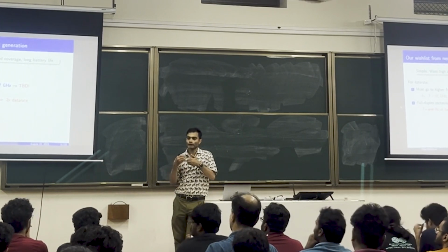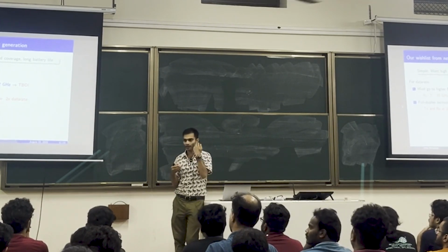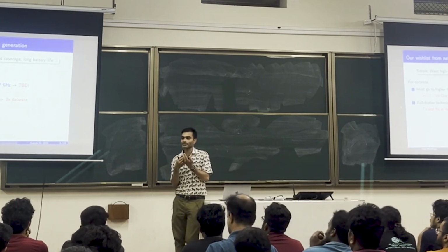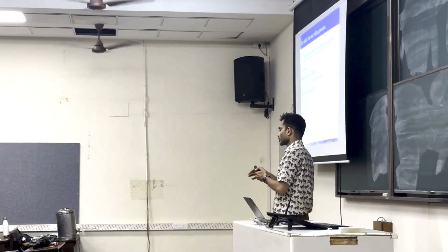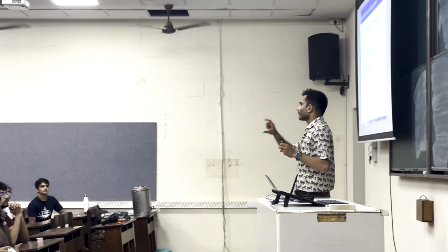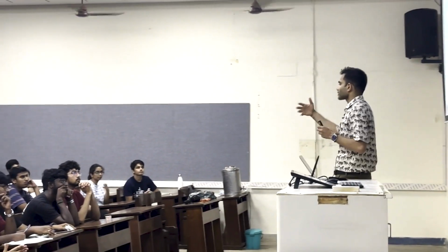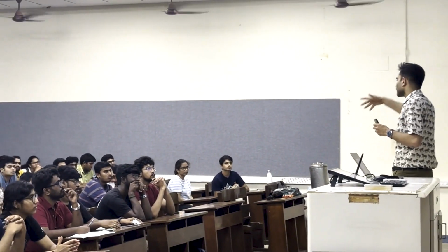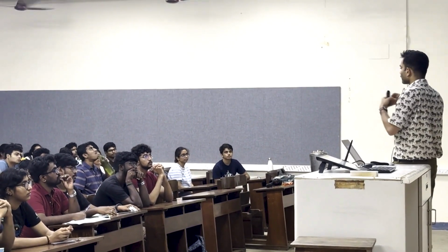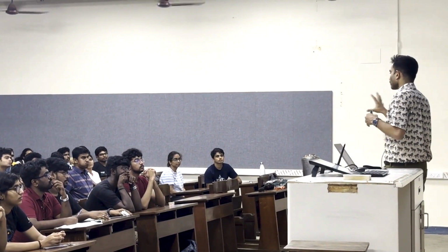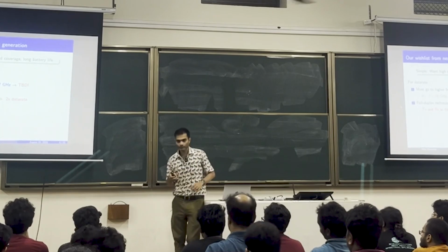Because I cannot talk and listen at the same time. If the antenna is transmitting, let us say, it cannot receive. Because there is a transmitter chain, a series of RF components, let's say a low noise amplifier, a capacitor, a whole bunch of things. So if I'm sending data over here, and I start getting data in the reverse direction, transmit power, imagine, is much higher, receive power is going to be much lower. So this difference in power levels can damage some components on the circuit. So that's why you separate it with isolators and things like that.